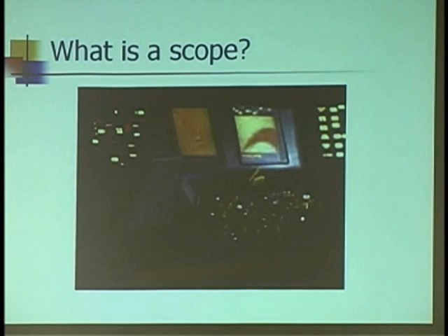Two things I'll tell you right off the bat. Scan tools have become very powerful, no doubt. But they only tell you what the module wants you to know. They're not always telling you the truth. But if I connect a scope to a sensor or a circuit or anything else for that matter, I'm going to get the truth. I'm going to get the reality of the situation.